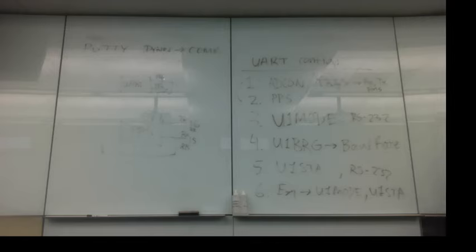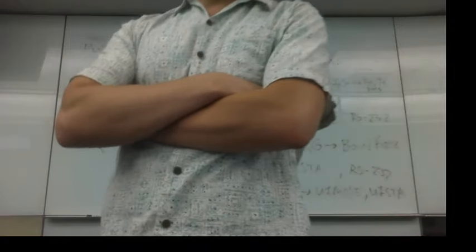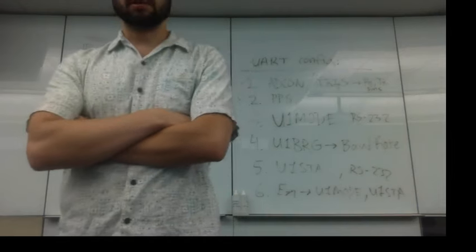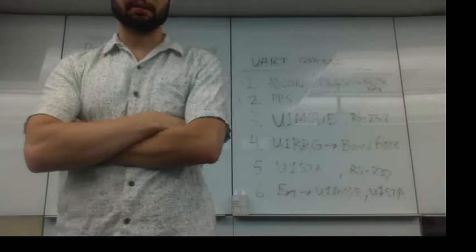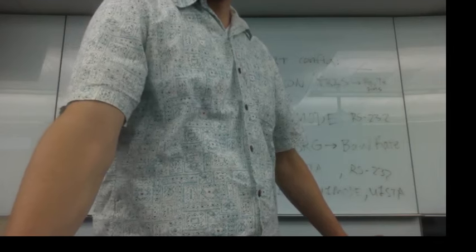But the problem is you have to have a terminal that will receive that fast, and specifically a terminal that will receive that data rate. I'm sure in some terminal programs you can just specify any integer or basically any floating point number for the baud rate. But for the most common baud rates, you have to get as close as possible. So what I really want to look at is the percent error. For 110 baud rate, there's 0 error, and for 250K baud rate, there's 0 error.